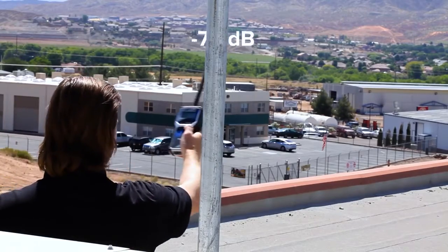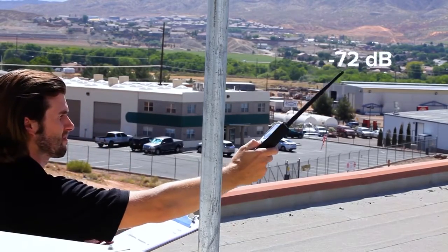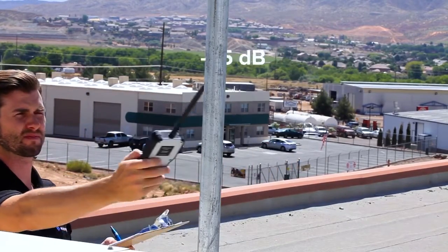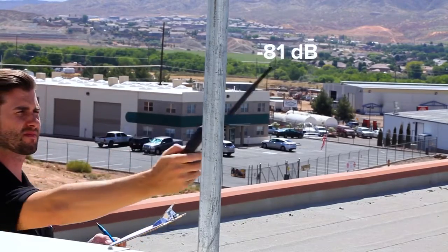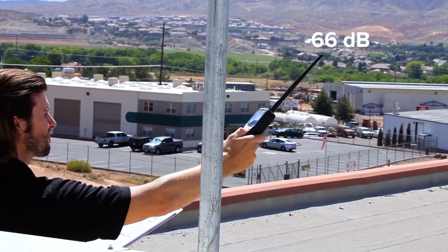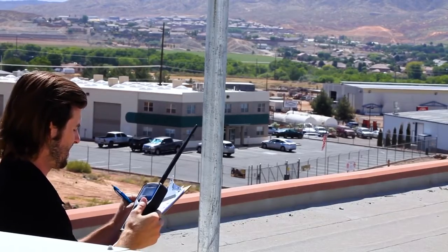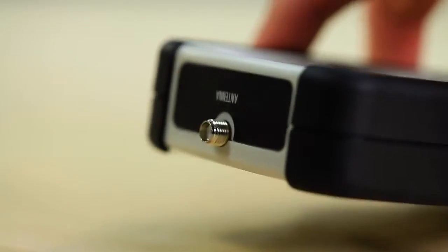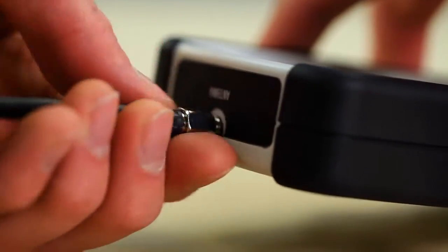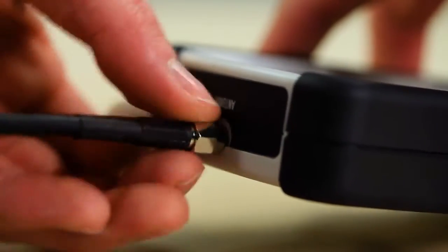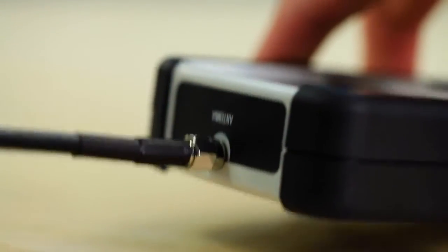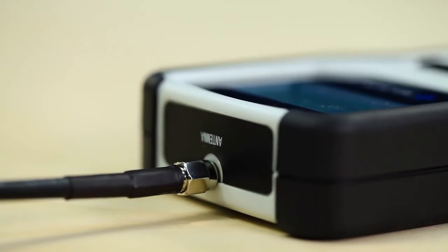You can also use a signal meter as a director to locate the cell tower or fine-tune your donor antenna. Using the included antenna, you can stand in a location and circle around 360 degrees to find the direction of strongest signal. You can also attach the signal meter to the end of a cable coming from the donor antenna to get an even more accurate reading of the incoming signal level to the amplifier. This is very useful, especially in a weak signal environment.